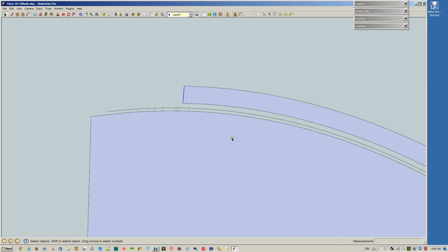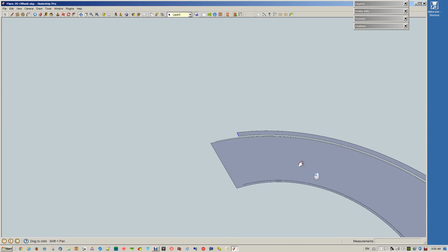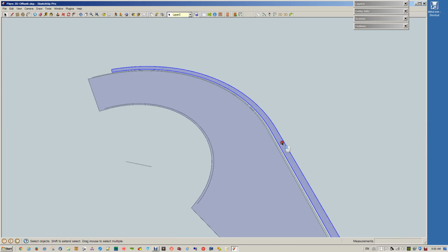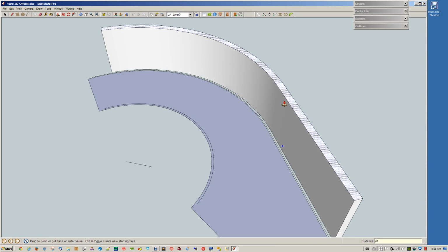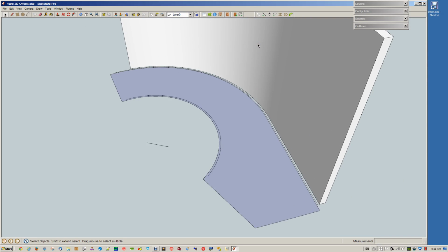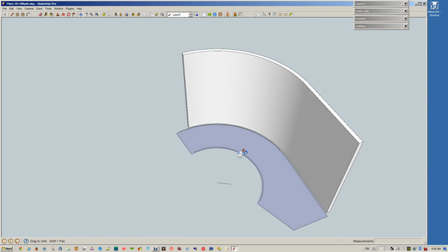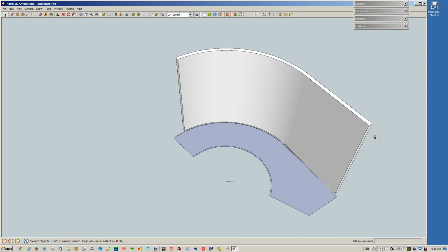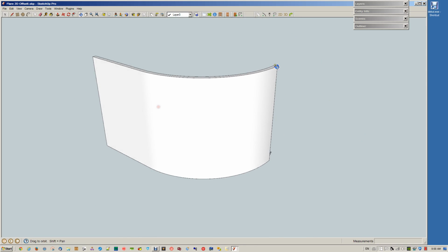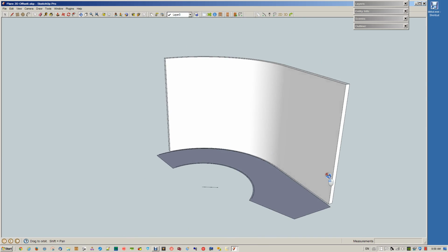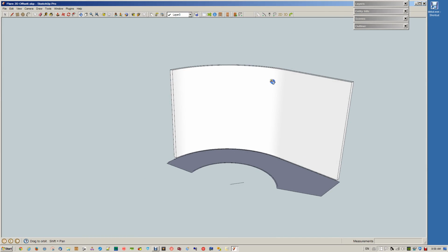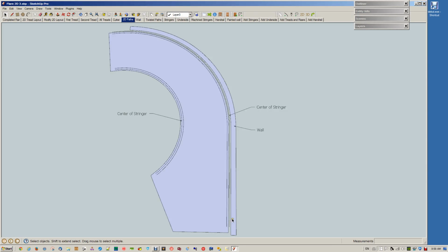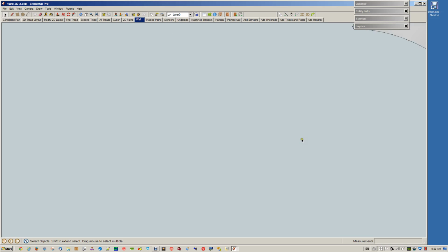So our total rise is 2800 millimeters. So now what I want to do is I'm going to build the wall by push pulling it up 2800 millimeters. By gluing those together to form a curve, what we ended up with is a smooth finished wall. Okay, let's go back to our main model. Here's our wall.